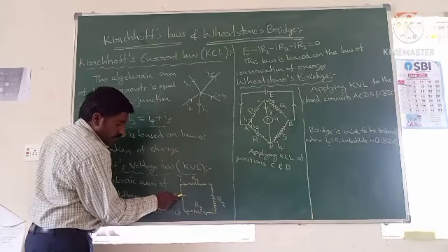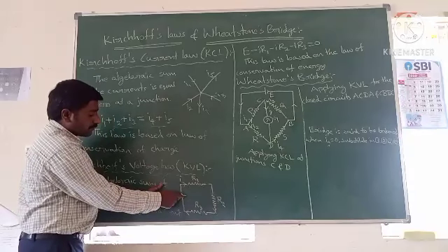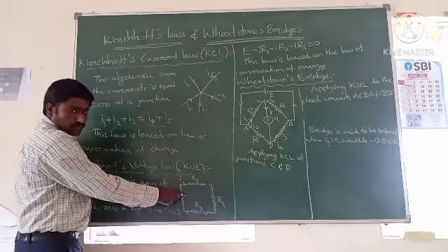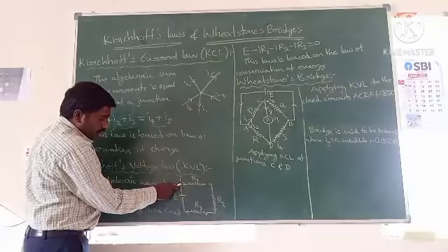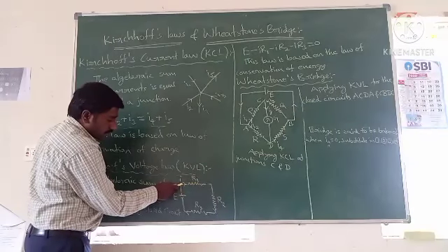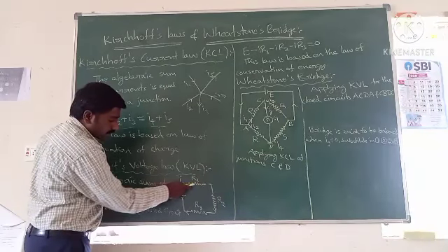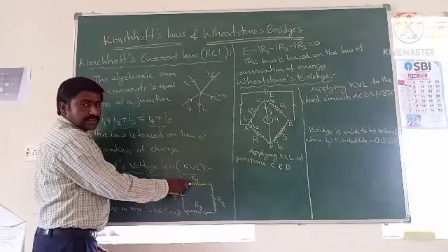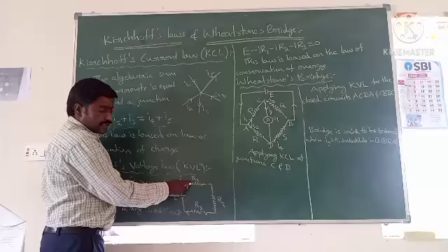So we are moving from the positive terminal. So the sign of the potential difference is plus E when we are starting from the positive. Next, we are moving along the current direction. So this is also the current direction. I direction is this one, and we are moving in the same direction as the current. In that case, the sign is negative, minus.